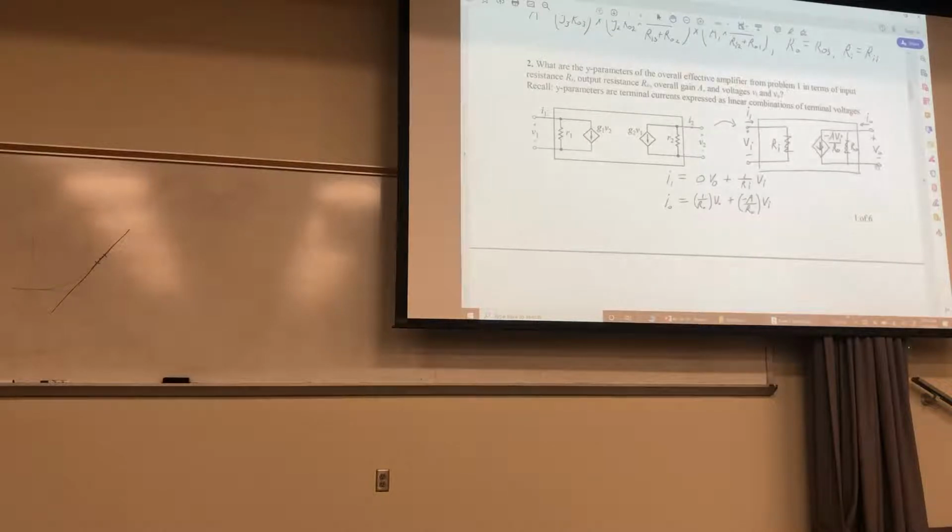This is sort of like a small signal model, because you can't go too far, otherwise you'll experience nonlinearities. And these elements, at least how we're modeling them, are linear: the current is proportional to voltage by this constant value. We're not saying that G1 is nonlinear. We're assuming it's a constant value, so it's linear. So that's done a lot in electronics.